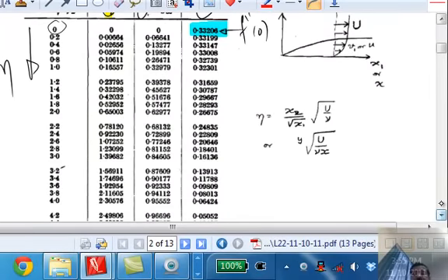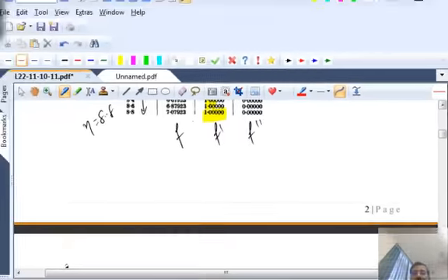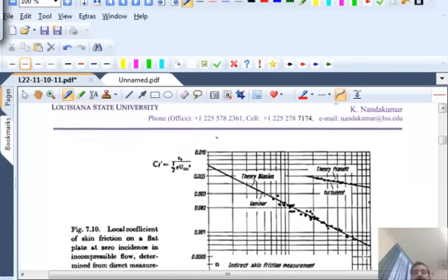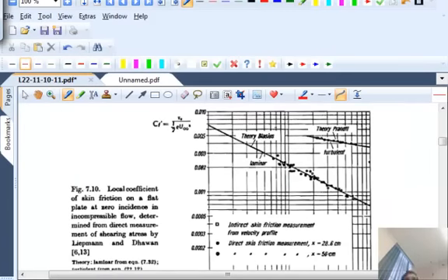Here is the table, and we saw how to use the table. But let me give you some results. This is the friction coefficient. Luckily, in this one, they did use Cf for the friction coefficient, which is defined as tau divided by 1/2 rho infinity U squared. And here you see experimentally direct skin friction measurement. Direct measurement means they're measuring locally what is the friction coefficient at certain distances. And the theory is the solid line.